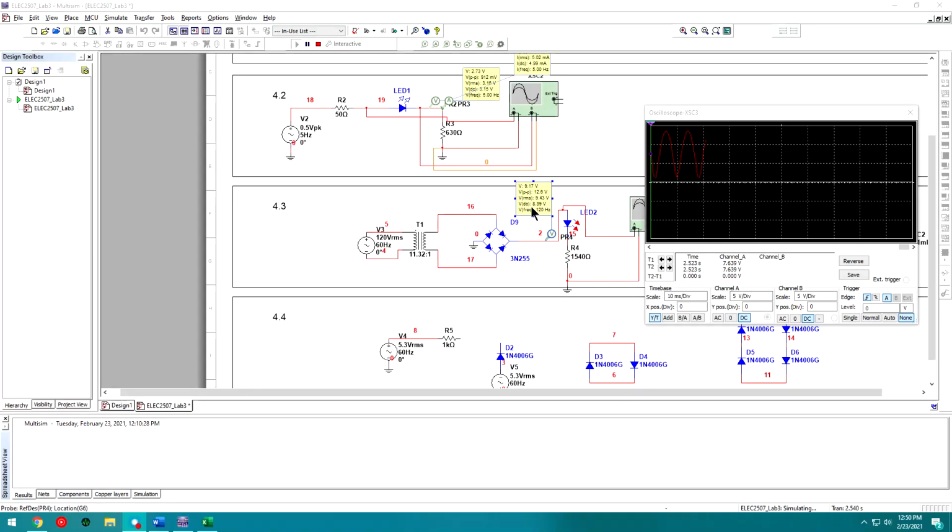You also notice that the frequency is doubled here. Why is that? It's because we rectified the bottom wave. So now every time the wave goes up and down, it's just restarting a new cycle. So this could work as a rudimentary frequency doubler. I know it wouldn't be a very good one, but this is something you will learn in later classes, and it's a cool application. This is how you could make a frequency doubler.